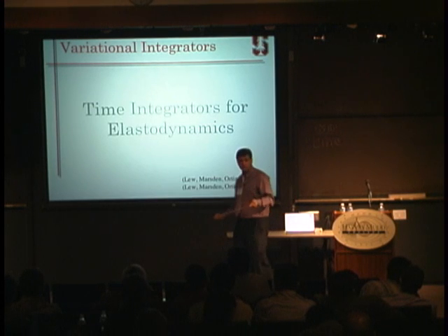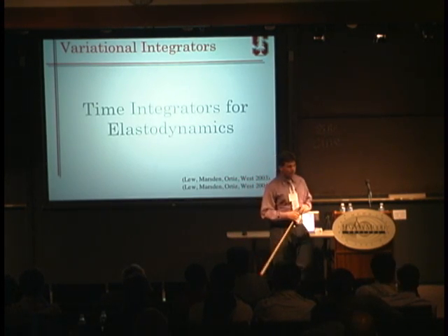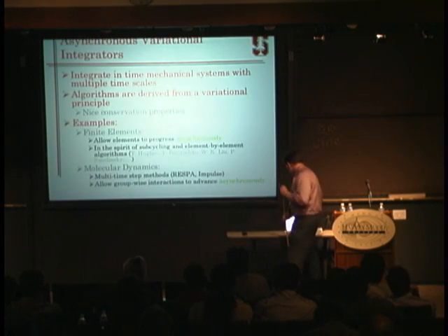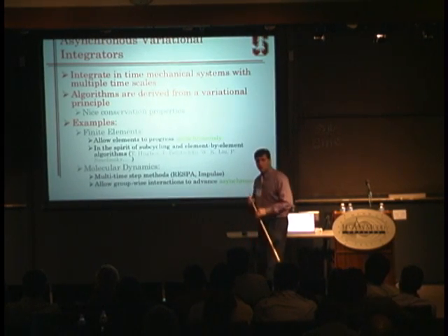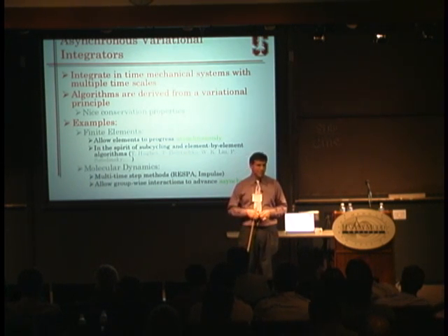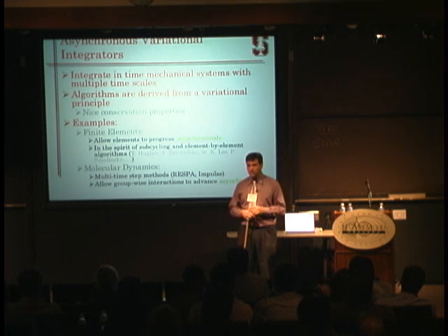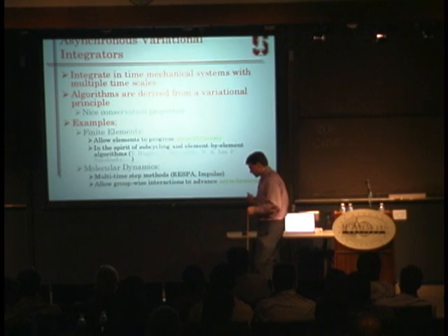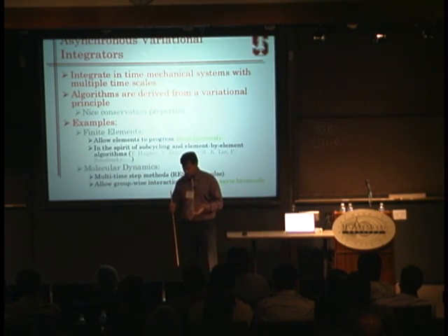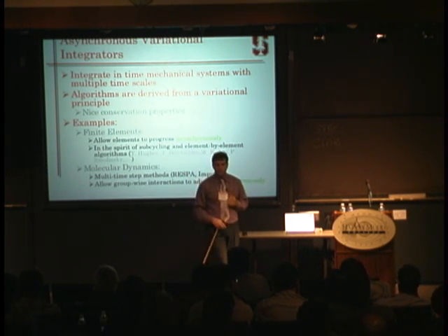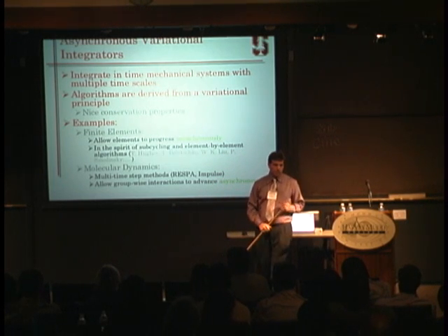Finally, I would like to conclude this talk by telling you a little bit about time integration and variational time integrators. So in particular, I'm going to talk about asynchronous variational integrators. This is just a class of integrators that you can generate within this theory. And the distinguishing feature is that you can integrate a mechanical system with different timescales depending on how stiff each one of the mechanisms inside your systems are.